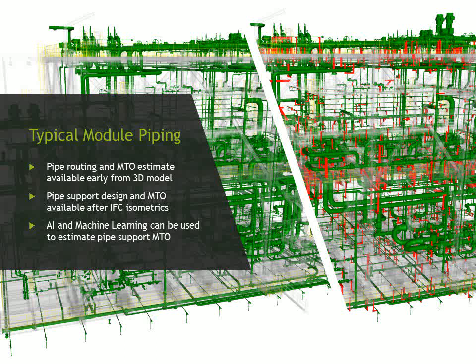Pipe support design is usually finalized after issued for construction. Piping isometrics are complete, usually lagging by a couple weeks. Material should already be on site by the time the pipe support IFC drawings are issued, which means the material takeoff should be provided many months before to allow for the procurement cycle to run its course.